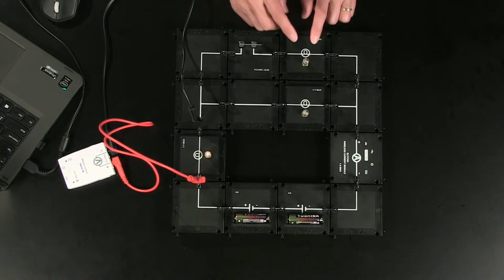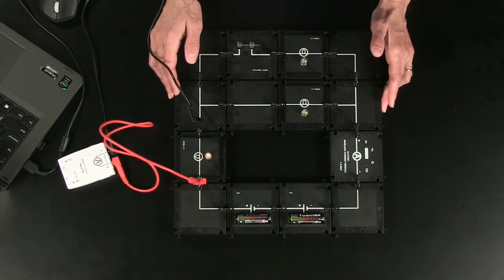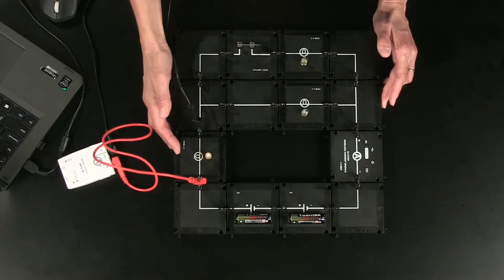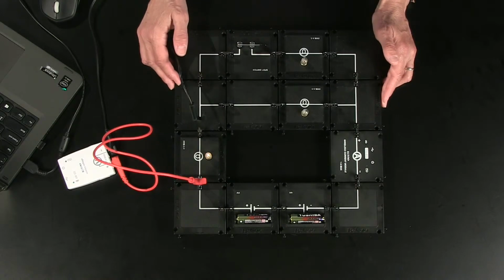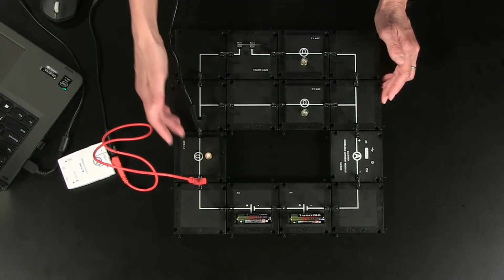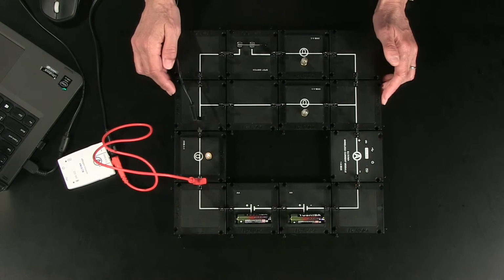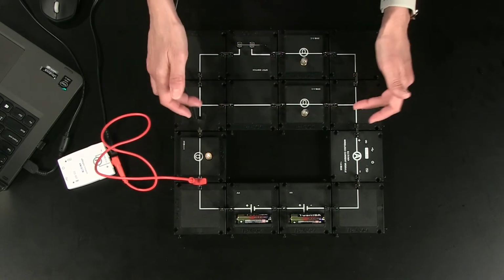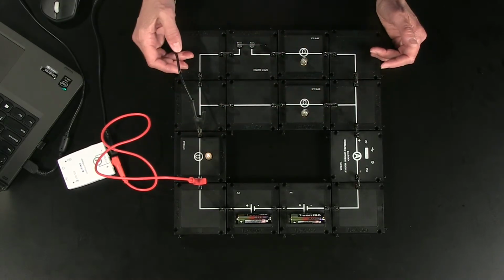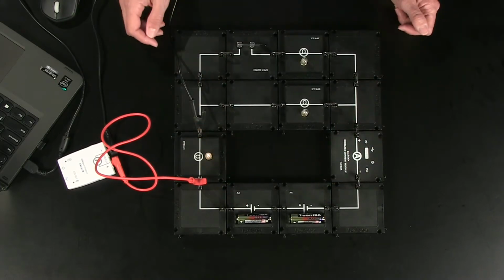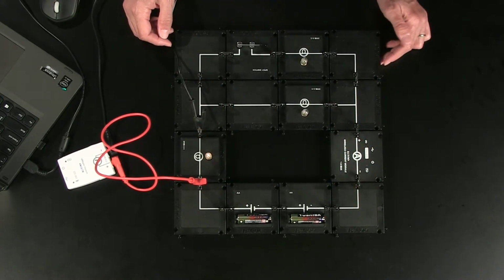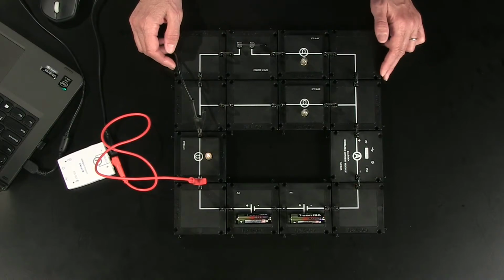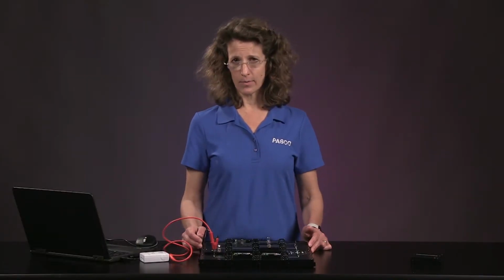What about for bulb 2? We observed that it got dimmer when the switch was closed. Since current through bulb 1 increases with the switch closed, the voltage drop also increases since it depends on the current and the resistance. If the voltage drop across bulb 1 is greater with the switch closed, the voltage drop across bulbs 2 and 3 must be less because we have the same battery source, and the sum of the voltage drops must equal the voltage from the batteries. Power depends on the square of the voltage divided by the resistance, so bulb 2 will be dimmer.